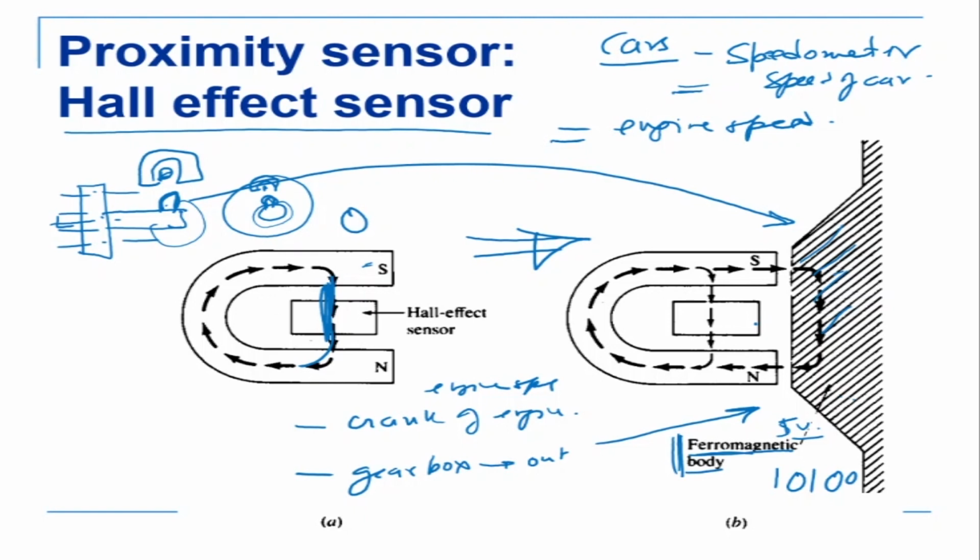Now when we talk about the DC motors, the brushless, what we call BLDC, I'll come to this subsequently. Brushless DC motors do not have brushes, so we need to sense the position of the armature. The armature position is to be sensed, and this armature position is sensed by putting 3 Hall effect sensors.